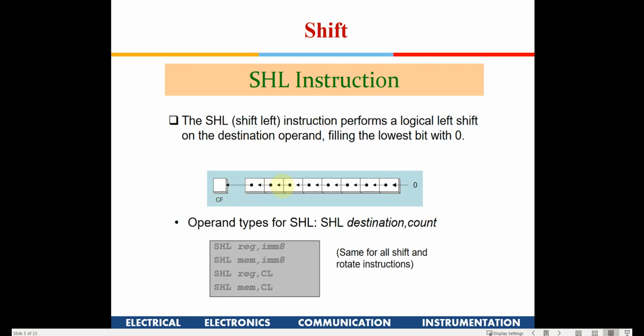Okay, or if you put 0 1 0 1 0 1 0 1 here everywhere and then you keep rotating it, then you will get a 2.5 megahertz clock. Okay, whereas you can use these shift registers also for controlling DC motors. We'll see those examples later on. In the lab, I guess there is one experiment on DC motors, so I would be explaining how those servo motors would work and how to control the direction of the servo motors using these shift registers and things like that. So these are some of the utilities of these kind of shift operations. Okay.